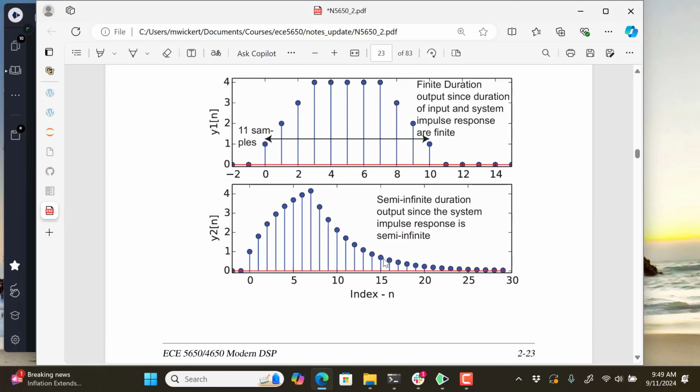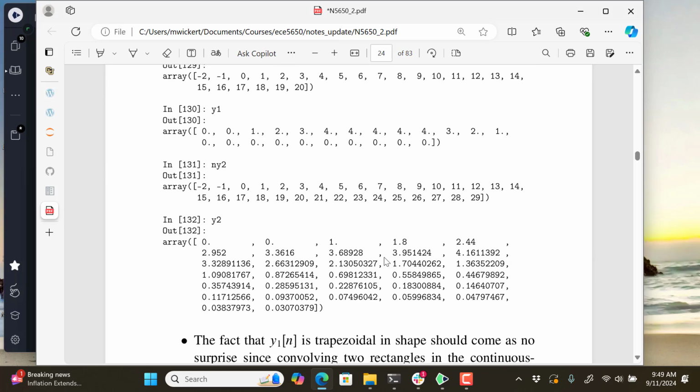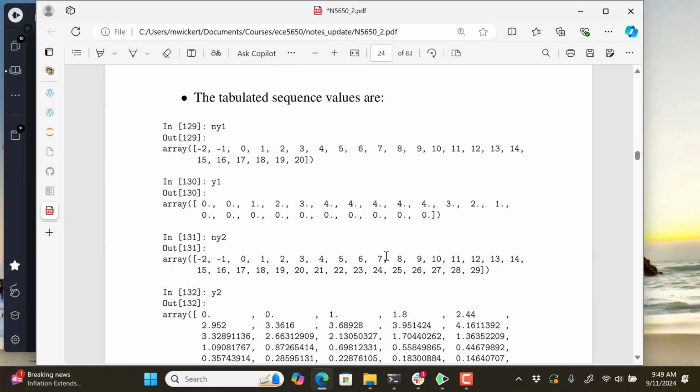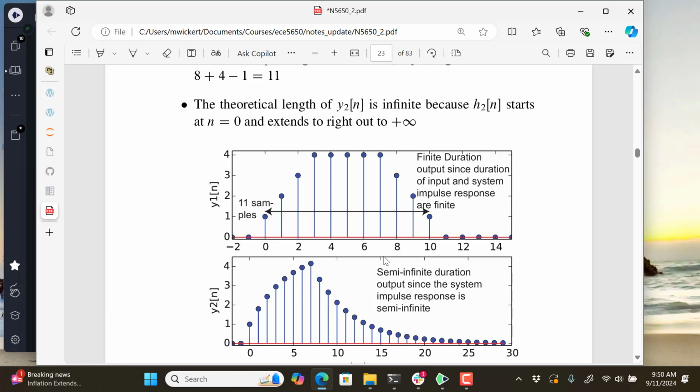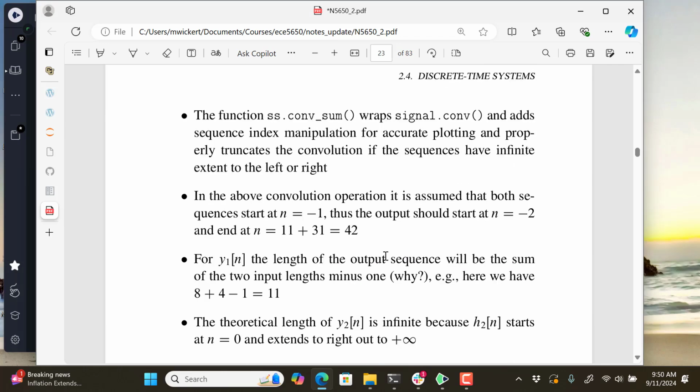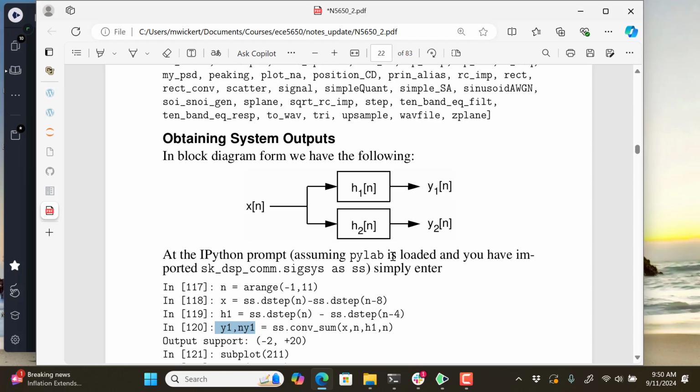And I'm not going to explain a whole lot because for the homework, I know the very last problem, I want you to use lfilter, so I want to be able to explain that today. I don't want you to try to use convolve on that. But as a handy function for just doing analysis, it's beautiful because it works. If it's a real-time thing, the lfilter is going to be what we're going to use all the time. But we have to have a difference equation representation, and right now you don't know the difference because I haven't quite got that far.